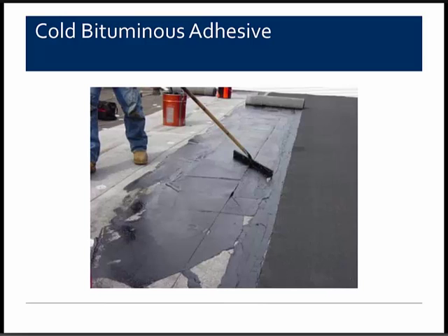The disadvantages of this is that sometimes, and particularly with the water-based solvents, these materials take a long time to flash off or to properly cure. So you've got to be careful about people walking over the materials before the material can flash off.